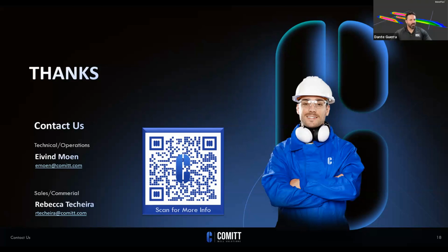Got it. And now on wellbore prep, there's a question from John talking about case study number 2. Was the cleanout performed to TD or more of a heel check? Yeah, so it performed to TD. In that specific case, sand was obviously coming into the well from a frac hit. So it was cleaned out to TD, and that's also on every well. I think operationally, that's maybe our biggest lesson learned throughout this whole process, as long as we've been running this, has been how to prep the well and making sure we get that correct. Because early on we maybe just pushed a bit to bottom, or our understanding of prepping the well was not what it is today.